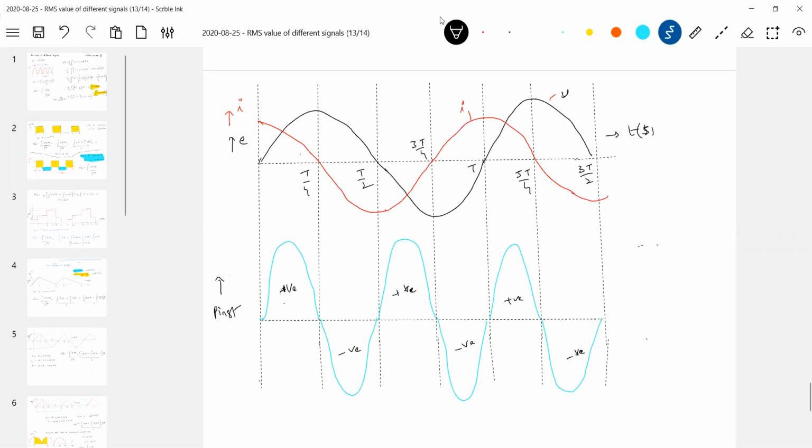So in one cycle, what actually happens? There'll be exchange of energy between the capacitor and the AC source. Altogether, how much power it has drawn from the source, that much power it will return back.